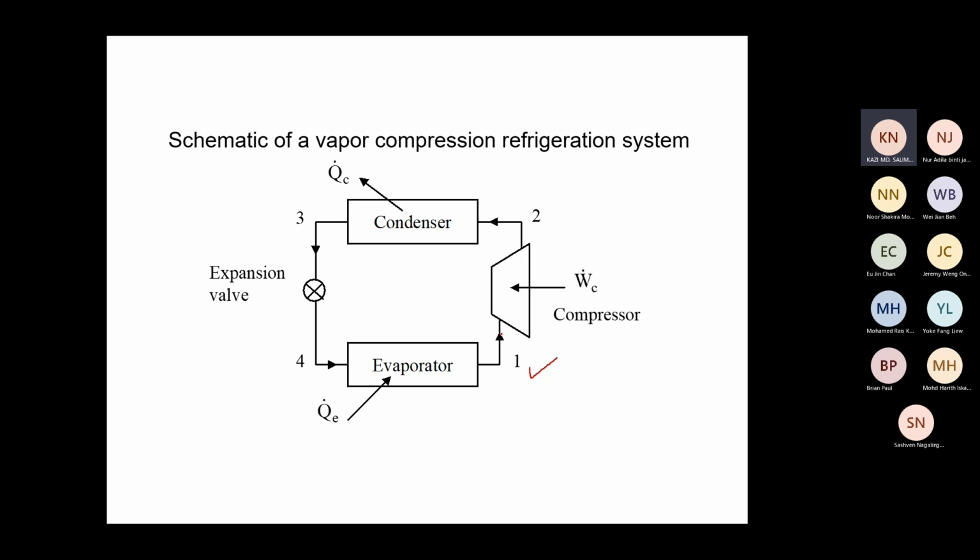See, the compressor inlet is there, and from the evaporator discharge it is coming there. There should be no liquid, and there should be no moisture content in it. If it is two-phase flow, the compressor cannot compress it, and then there will be vibration as well as surging, and then the compressor